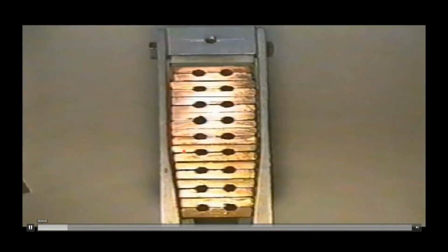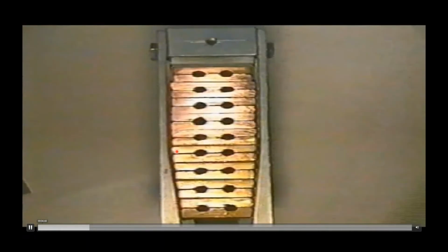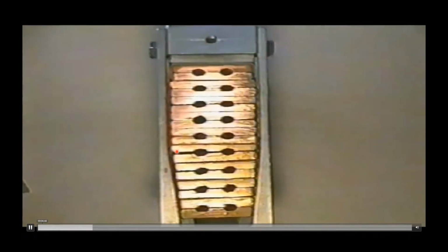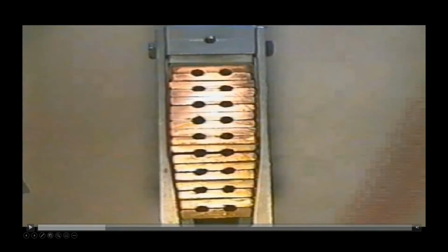That means that it's very easy to damage mechanically your interturn insulation, which is sitting in between copper turns. But also, this movement can cause copper dusting. And as we all know, copper is very conductive. Therefore, you might end up with the conductive debris in the slot section causing further problems. That's why, and let me emphasize that here, bearing gear could be a killer, and it often is. Alright, there's a few minutes of this movie. Let me stop that and let's continue with the presentation, but I think you've seen enough. Alright?